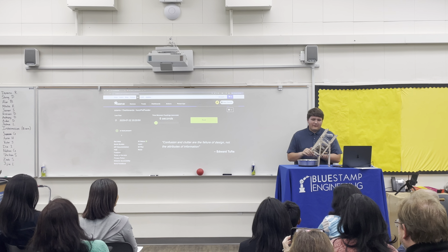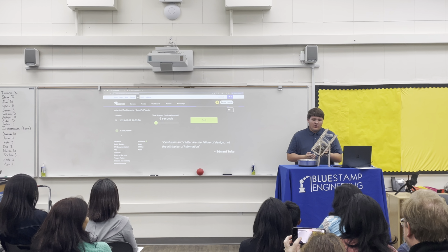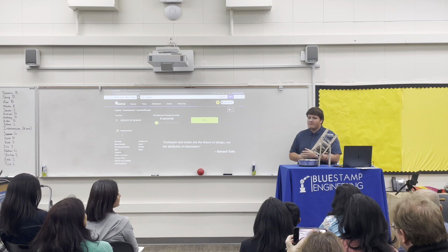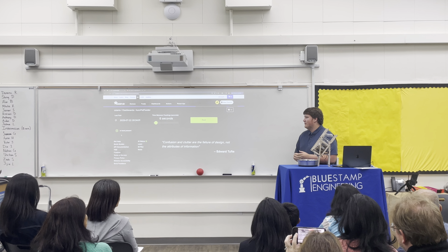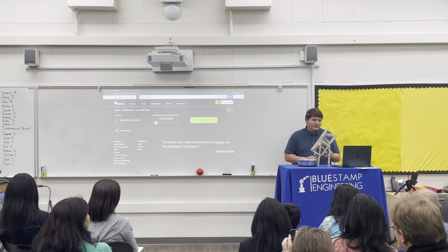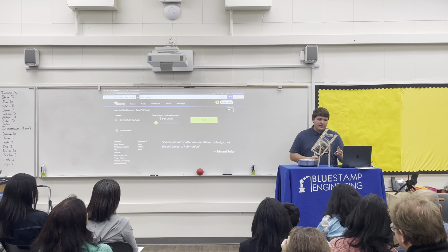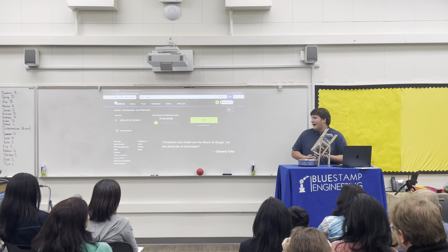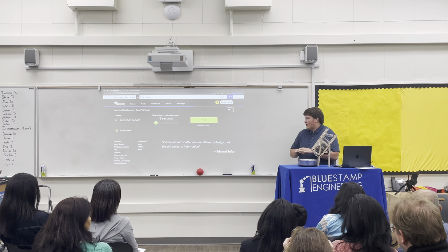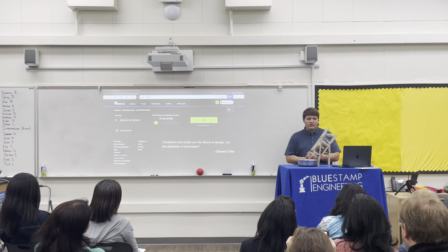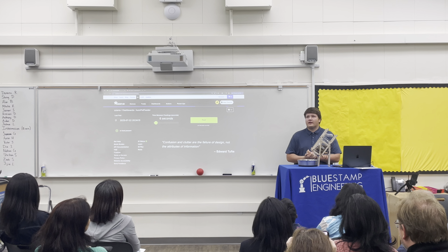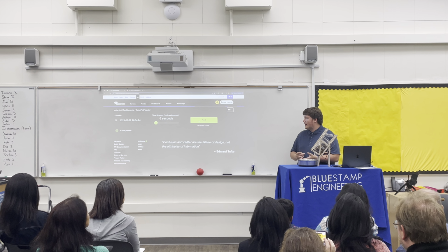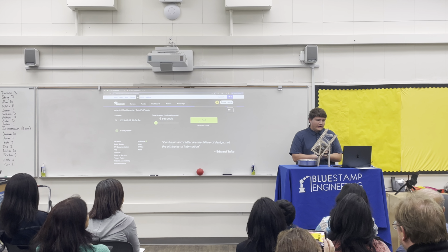And so, the challenges I faced during the project: originally I had a command called delay in my system, which would stop all my code and wait like 2 minutes between feedings. However, I have a feed button and a slider between feedings, and that wouldn't work, because if I click the feed button, it just wouldn't work, as it would be paused, the parent code would not run. So I had to switch to a different type of code called millis, which counts upwards constantly while letting everything else run in the background, and that allowed everything to work.